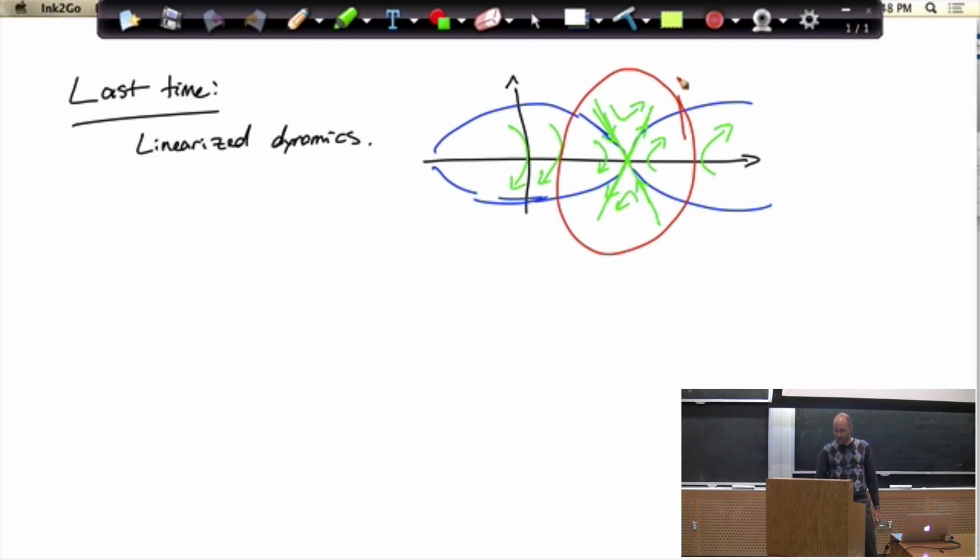And one of the things we're going to do soon, for instance, with that region of attraction code that I just alluded to, is be able to calculate that more precisely. You learned the definition of a region of attraction, but you could ask the question: if I design a linear controller for my nonlinear system, for what initial conditions does it work? Is the closed loop system going to be stable to this fixed point? You could ask for the region of attraction of this fixed point under the closed loop system, and that would tell me when the linear controller is doing the right thing. We're going to talk about that in detail next time, okay?